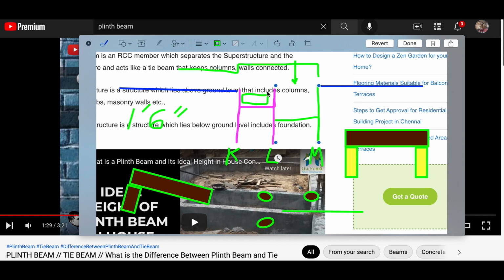And all we have to do is lose these, and now we've got two separate buildings wanting to react differently because we've got a floor now, an internal slab that's not supported the way it was intended to be supported, or the way it was built to be supported with the 1'6" elevation change.